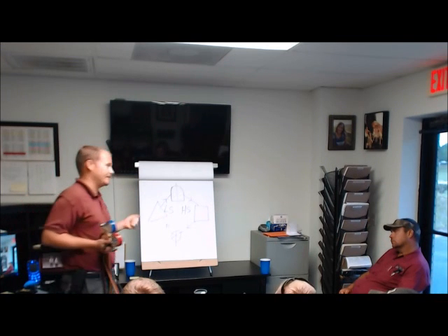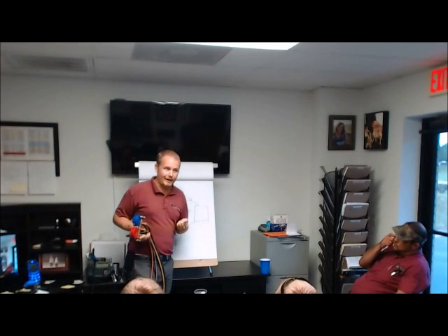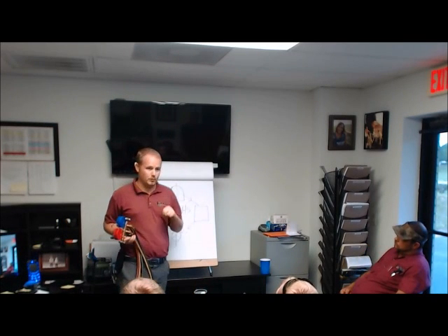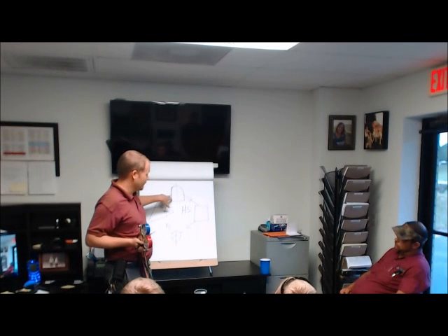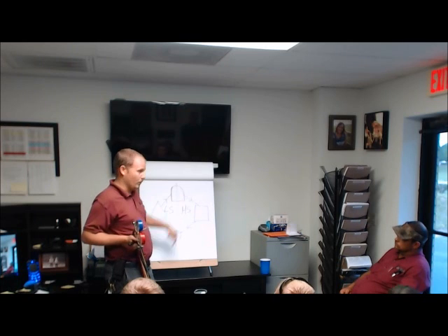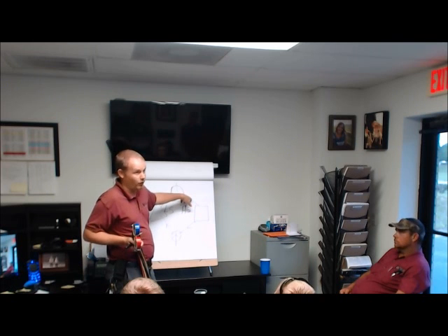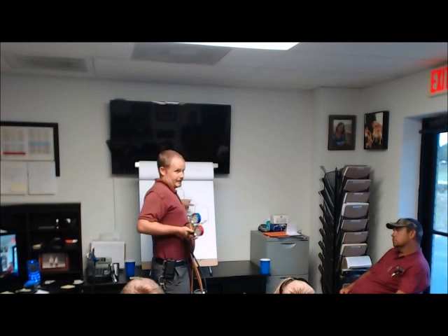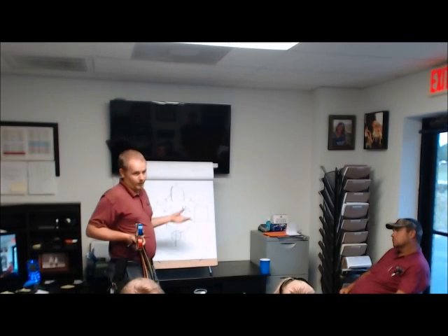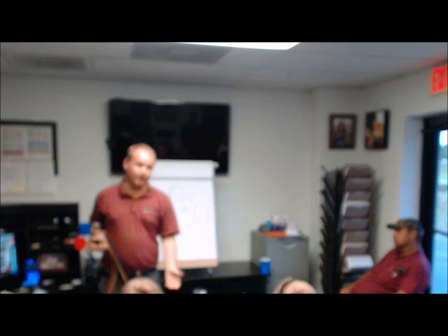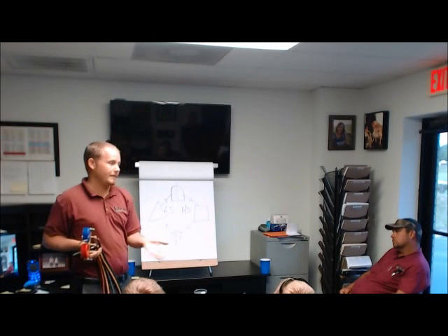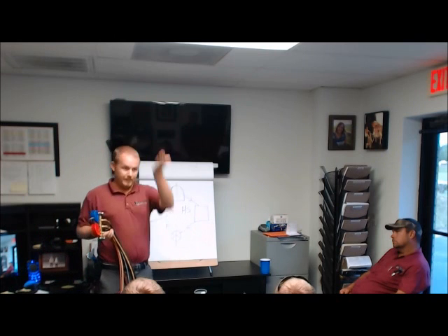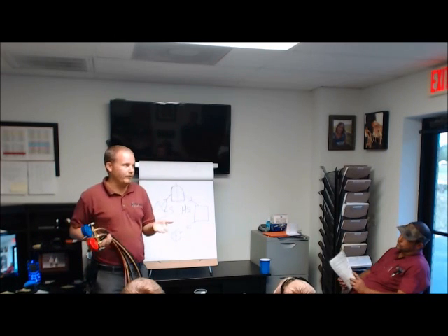Okay? Because let's give an example. Let's say you're on a commercial rooftop package unit, and a lot of times, where will the ports be on a commercial rooftop package unit? Which two lines? Discharge. You'll have a port here, and you'll have a port here. Okay? What happens if you're trying to take your subcool here? You're not going to get a true reading. You're not going to get a reading hardly at all. Because you're not going to get a subcool, because it's going to be the same temperature, or actually a lot higher temperature, because it's actually still in the vapor state, which means the temperature of that line is going to be much higher than saturation. When any matter's in the vapor state, it's going to be higher than saturation. And there's no real way of knowing how much higher it's going to be.